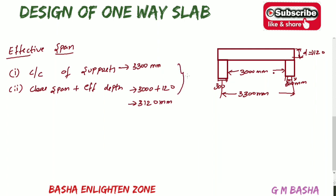Here you consider whichever value is less, between center to center of the supports and clear span plus effective depth. Out of these two, 3120 is the lesser value, therefore we are fixing the effective span as 3.12 in meters. That is the procedure for finding the effective span. And remember one more point: if they mention the width of the supports as 300 like that, then you can take down this step.